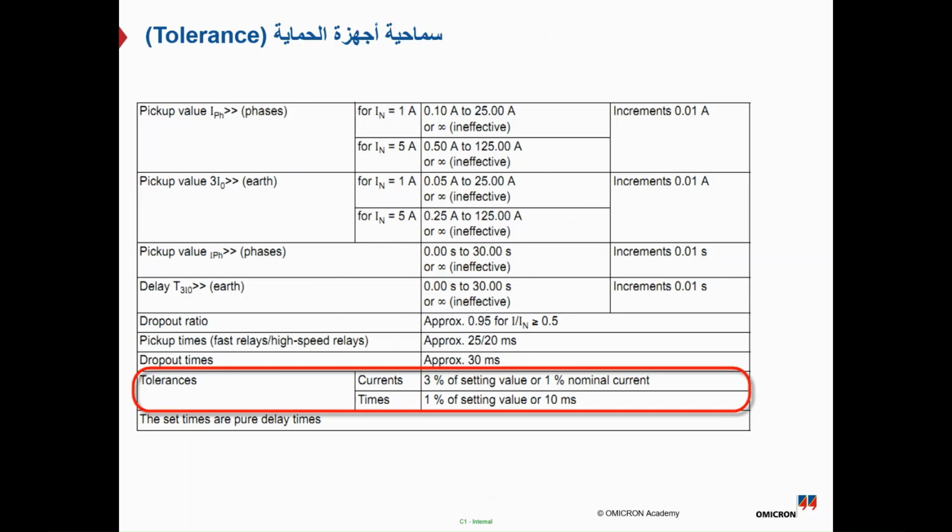But if you are building your customized test plan using general test modules like the ramping module or the test sequence module, you have to define, based on the setting, whichever is greater, the absolute or the relative one, as the tolerance band for result assessment. Is it pass or fail based on the protection relay manual.